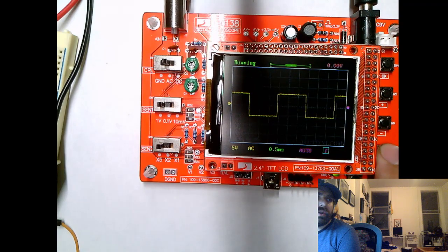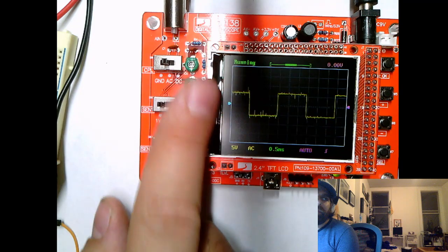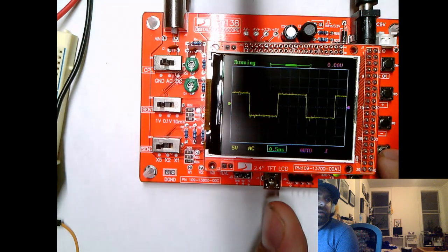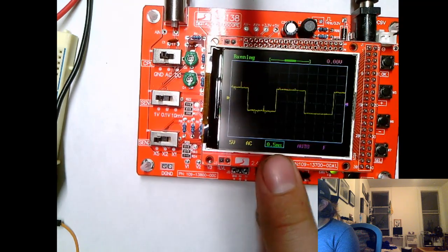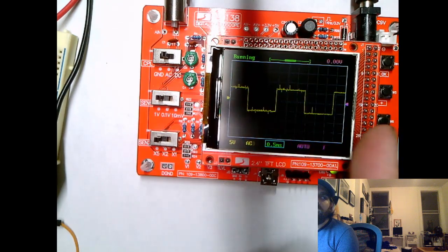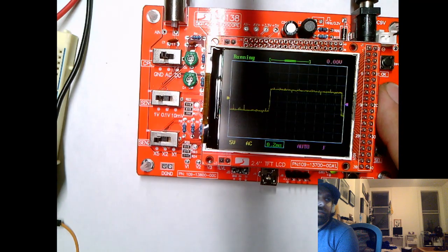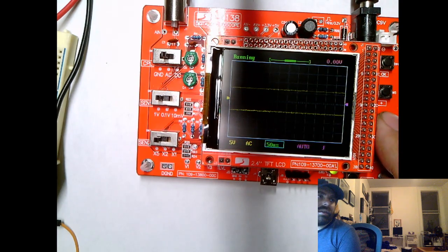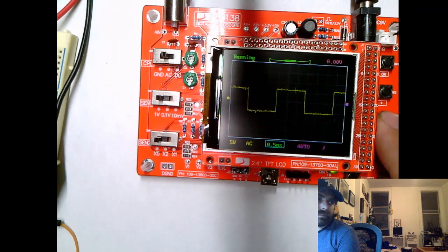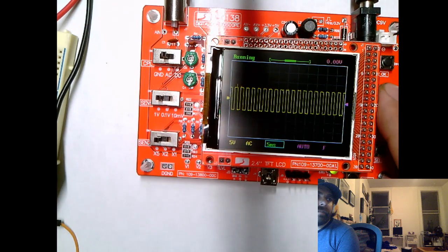So I already showed you that I can move the signal up and down. This is my vertical position arrow, so this allows me to shift the signal up or down. If I select the time, right now I'm at 0.5 milliseconds. This is our x-axis, my horizontal. So every block is 5 milliseconds. I can change this, and I can make every block 50 microseconds. This is a lot smaller. I can go the other way, and this is 1 millisecond, 2 milliseconds, etc.